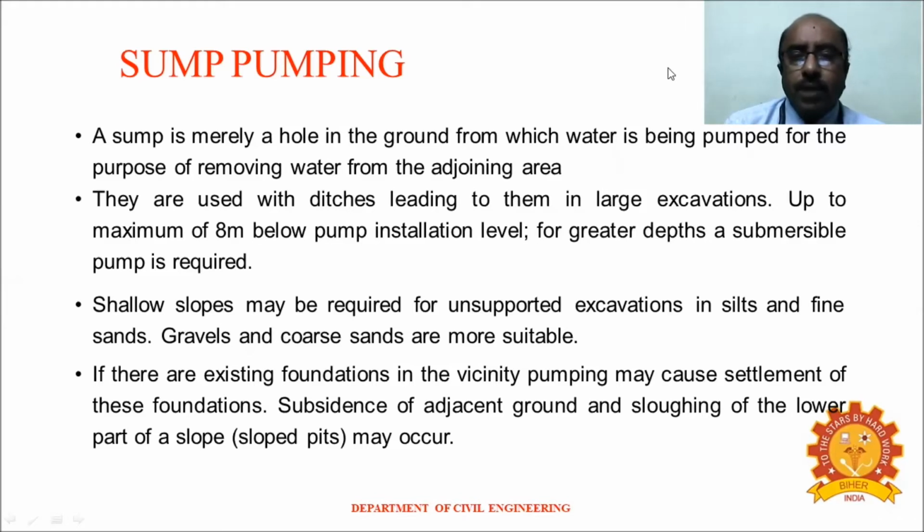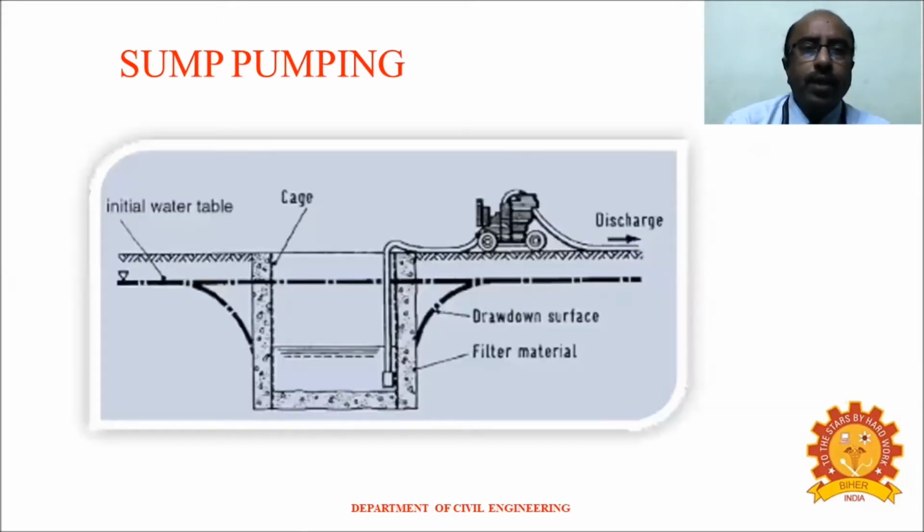Shallow slopes may be required for unsupported excavation in silts and fine sand. In gravels also, sump pumping is more suitable. If there are existing foundations in the vicinity, pumping may cause settlement of these foundations. So we should be very careful in pumping. This picture shows the simple sump pumping technique, where we have the sump, and inside we have the suction pipe with the filter medium, and this is the pump.